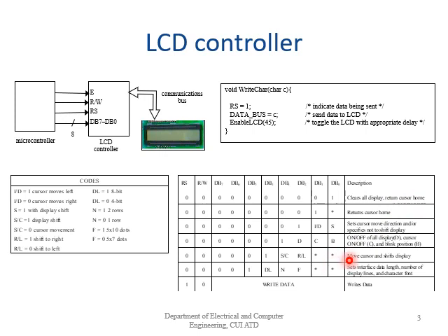So for example, if you want to move cursor and shift display, we need to set DB4 to 1 and DB3 to S/C. So we can see here S/C: if 1, display shift; if 0, cursor movement. So you can set it 0 or 1. If however we want to move the cursor, we have to set it 0.